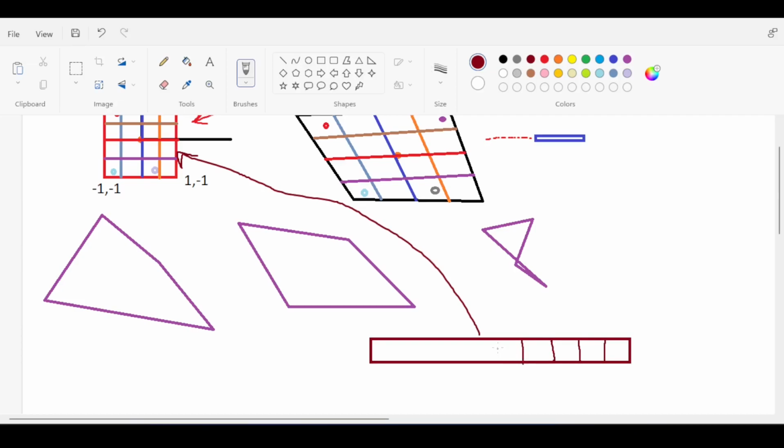Now, by the way, there is also an isoparametric element for a triangle. I don't want to bother you with this, but very quickly, the isoparametric element of a triangle, amongst others, is a right angle triangle. You can distribute this to find a better aspect ratio. And Robot does allow you to see this. Robot gives you those tools, and I will show you those tools today.